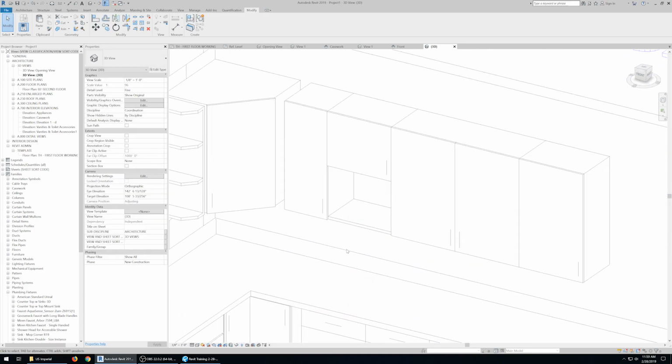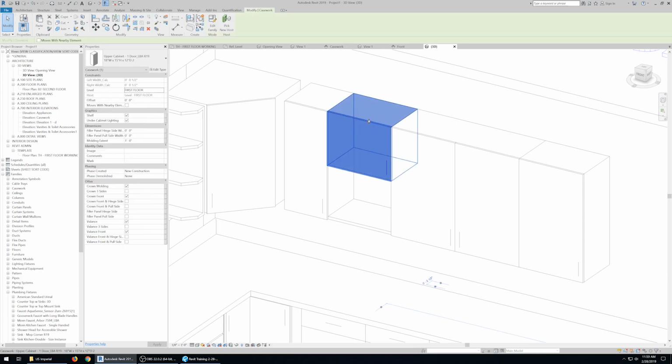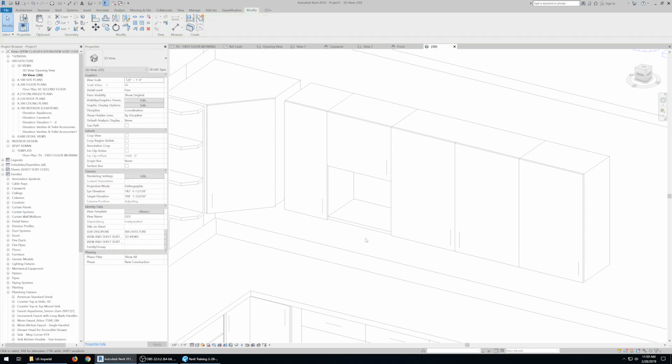There you go. But for this case, you could just use that shelf in the family and set it, like, if you turn it off, then I don't have to draw it every single time when it pops out. Correct. If I would ask the question of, will I have this same family that I need 50 times in my model? If I do, edit the family, do a save as, edit the family to have an open shelf below it, and then it will be easily 50 times. But if it's only once, you saw how quickly I was able just to do that one time, and now I'm done. I don't have to do anything else.